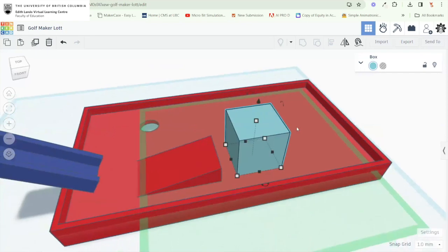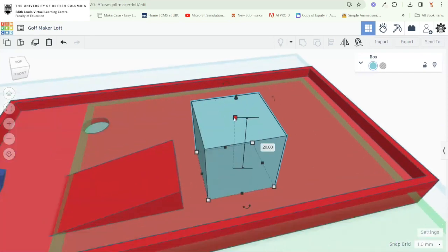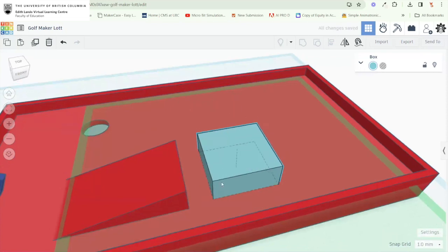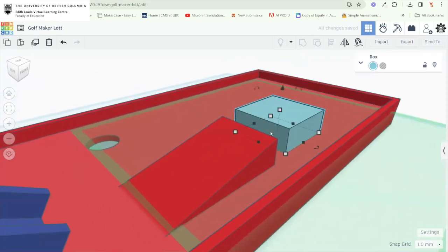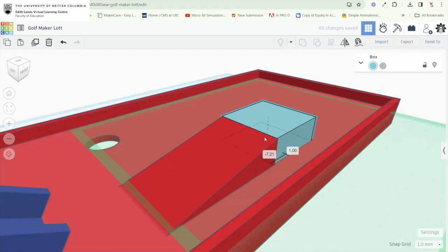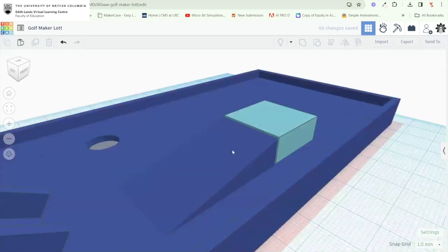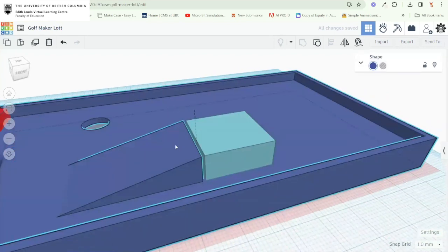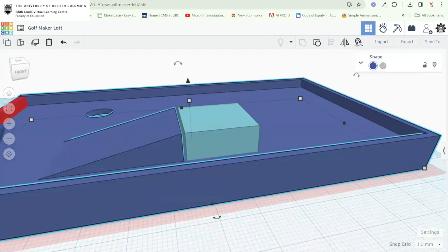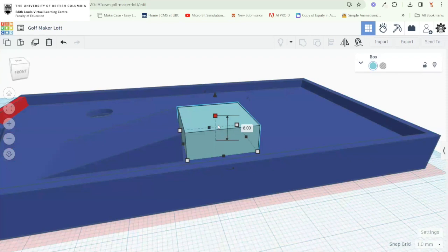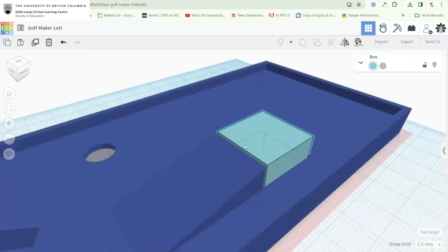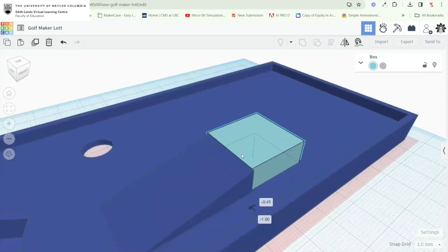Now there's other ways to do this, but I think using a square is going to be a good way to understand the process. So lower the square first of all to the height of your jump. Now my jump, I think my jump is 8 millimeters. Let me go back. Yeah, 8 in height. I'm just looking back on the chat. So the height of this jump right here is 8 millimeters. So I'm going to make the height of my cube 8 mils, and I'm just going to match it up with the jump.